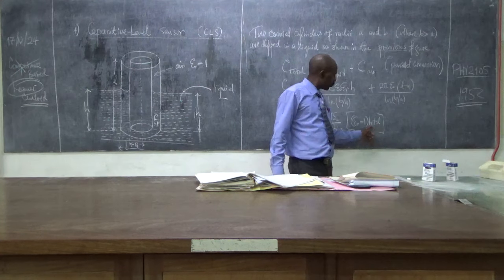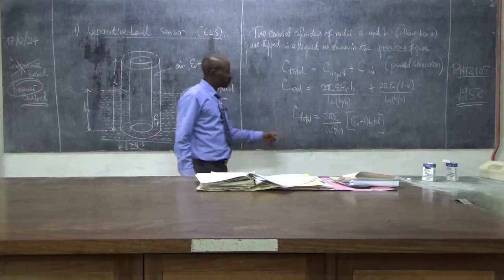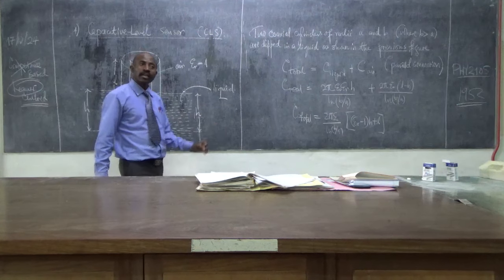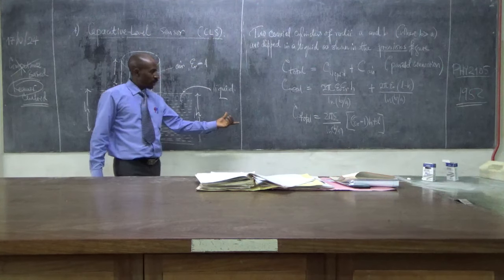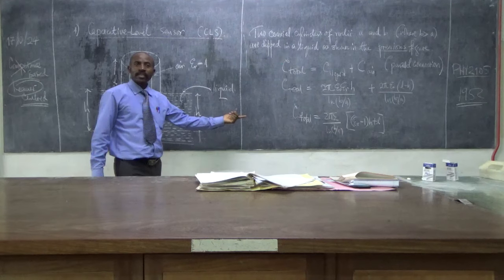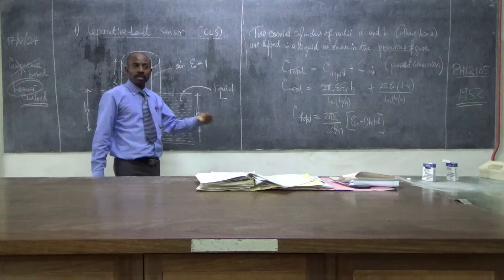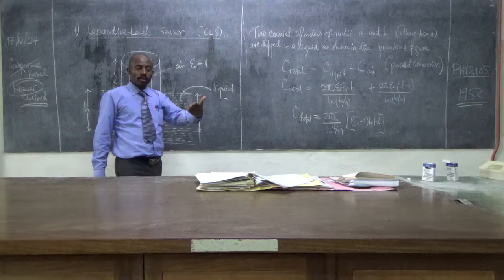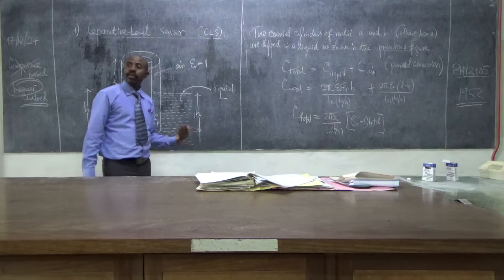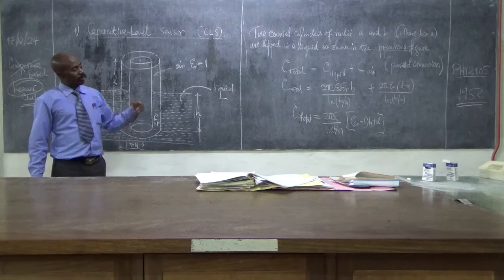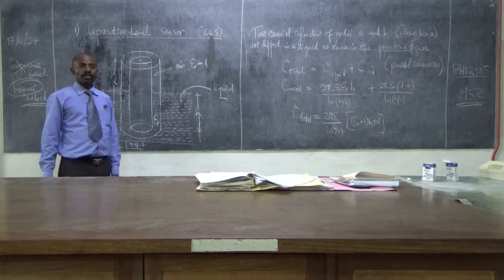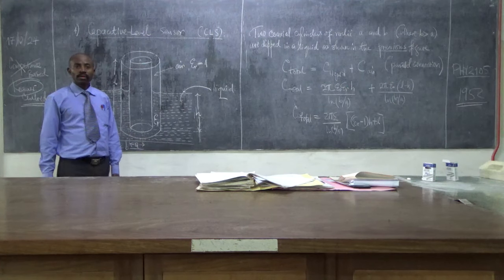So it's this H which will be changing the total capacitance. And then if you now calibrate the capacitance or the voltage to be able to be measured or displayed, then you get a value being displayed. And you can translate that into the fuel you are having in your fuel tank.